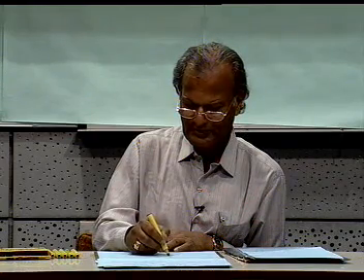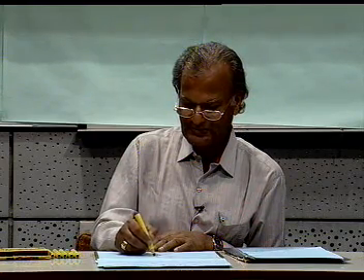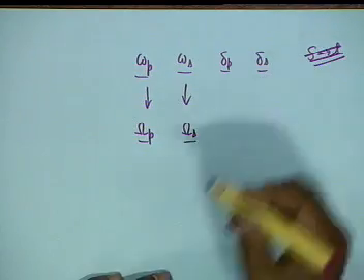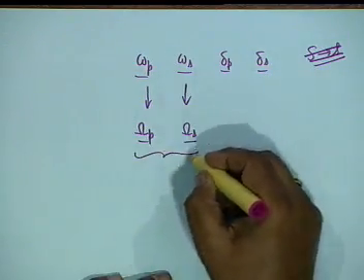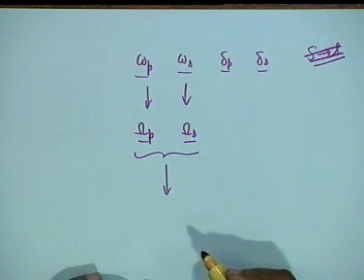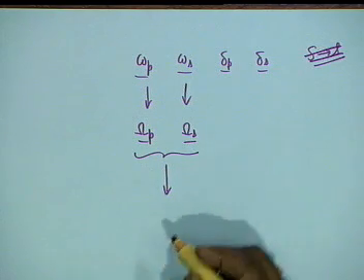And what you do is convert this into omega p's and omega s's, from which delta p and delta s remain the same. From this you find the normalized analog low pass filter.